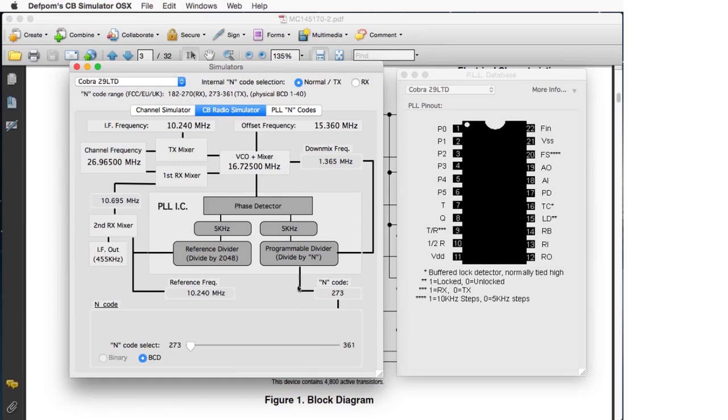You also have to make sure that things like the encodes going to the PLL are correct as per the requirements of the PLL and the particular radio. So if the encode is wrong, so it's got a bridge trace or something like that, or there's a broken connection, or a bad solder joint or something like that, this could be wrong, which throws the whole lot out again. Right? But it's all about mixing these frequencies together. It's all mathematics, and it's not hard mathematics, right? The actual PLL theory section, as long as you understand how the PLL internals work, and this is really simplified, but that is the basic function.